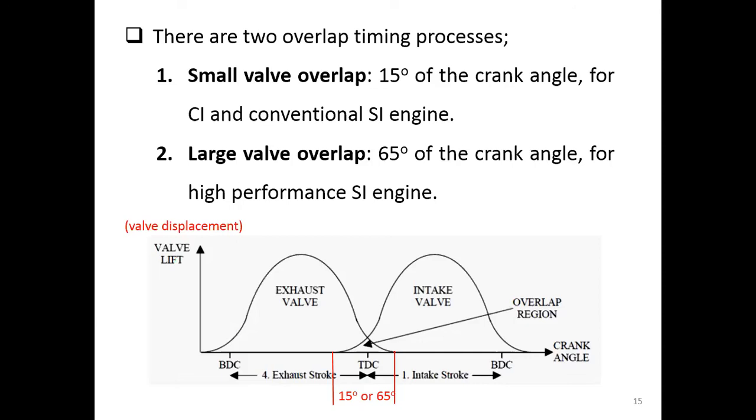Okay, from the circle we can make a plot of the valve timing like this, by representing the valve lift, or the lift of the valve, when it is closed and open, against the crank angle position here.